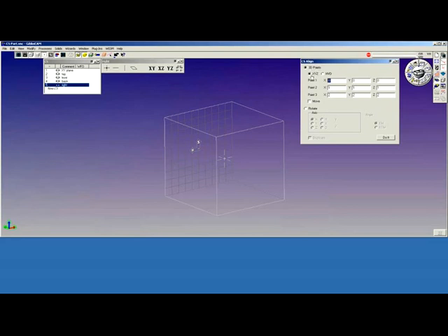The points can be defined as XYZ, absolute coordinates, or HVD, incremental coordinates. By defining 3 points in space, I can generate or align a coordinate system through those 3 points, giving me a compound angle or a skewed CS.